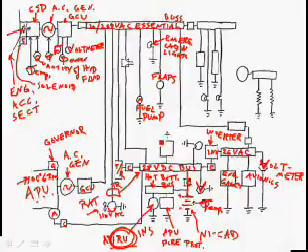On the Boeing 777, like I told you before, some of the things run off of DC. So backup gauges is what we're going to write here. Backup gauges. That might be really nice to run it off the 28 volt DC bus, because we can power it off of the battery, and if the RAT's working, or the APU generator or the main generator on the engine are running, we can run it through transformer rectifiers and keep this bus powered. So that might be a good place to run backup gauges, and maybe that would be a really good place to have the cockpit lights.